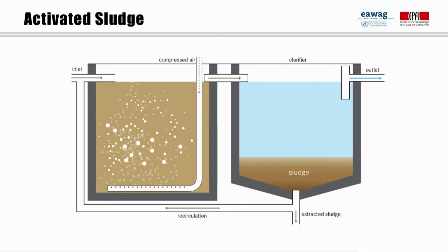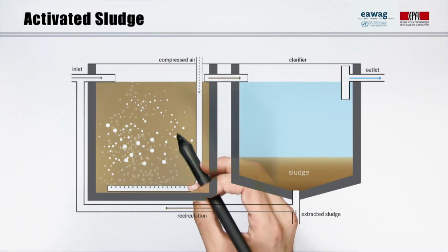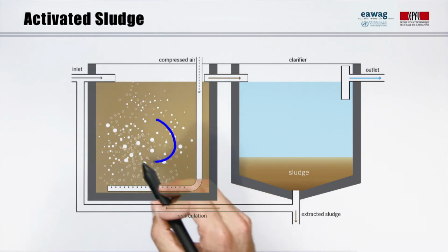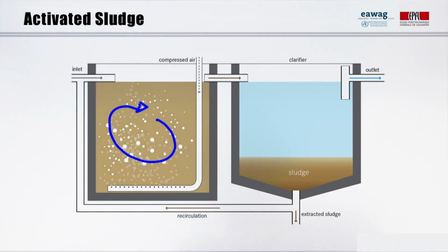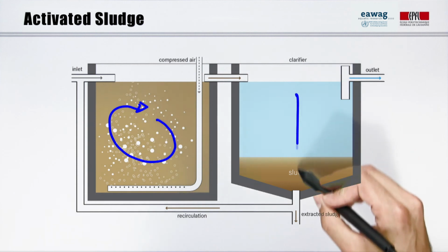To maintain aerobic conditions and to keep the activated sludge suspended, a continuous and well-timed supply of oxygen is required. Aeration and mixing can be provided by pumping air or oxygen into the tank or by surface aerators. Agglomerations of sludge particles, called flocs, form in the aerated tank and are removed in a settler, called in that case secondary clarifier.